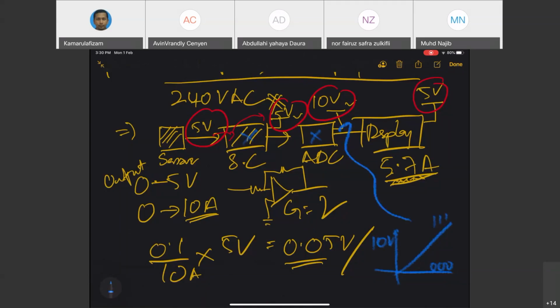The information that you basically receive from signal conditioner is just 5 volt, okay. Maximum scale. When this thing goes to ADC, your information will be truncated at this level, and you will use only half of the ADC bandwidth. That's a problem, okay. That's why you need to work to the maximum. You need to amplify the input signal to the maximum operating voltage, so that when you work in a range of